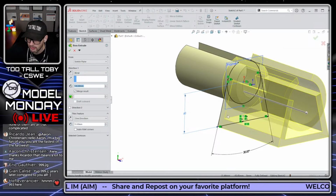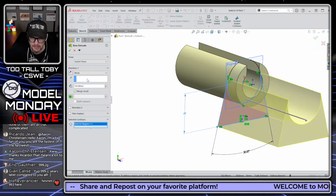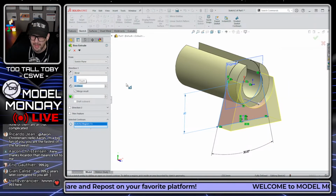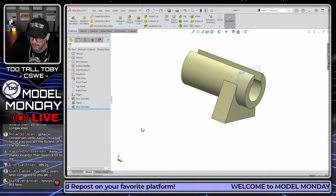And now we can choose extrude, and this is not going to be a thin feature. I'm going to do selected contours. We're going to pick this contour here, and then we are going to say that's going to have a width of 30 and right mouse button, reverse direction, right mouse button. There we go. There's our leg one.